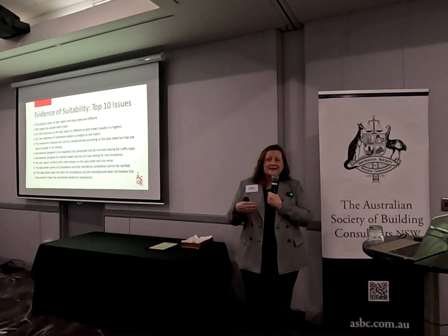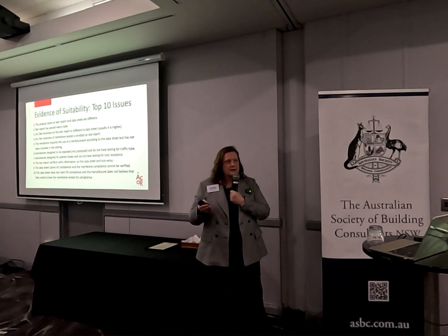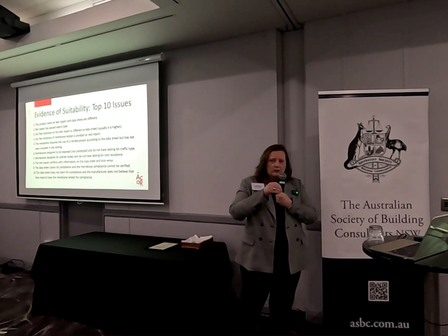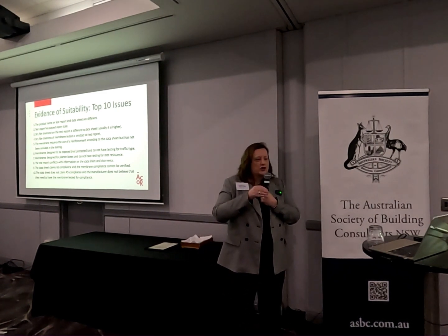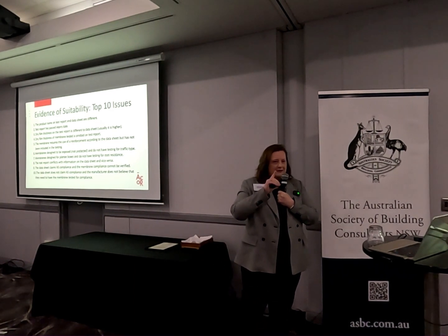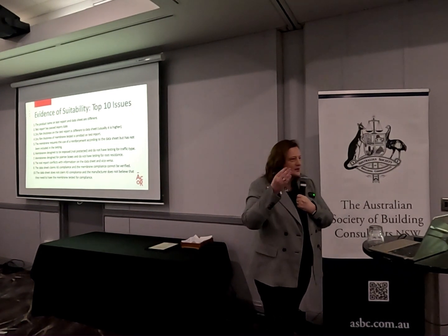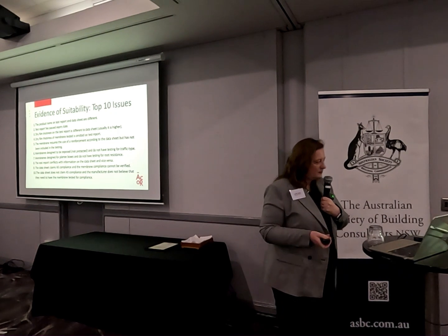QUV test, which is an accelerated UV aging exposure test. It has a requirement of 1,000 hours. In Sydney, I Googled it, our average daylight hours is 2.5 times that for 1 year. So it's not very stringent, but some of them aren't even testing that.